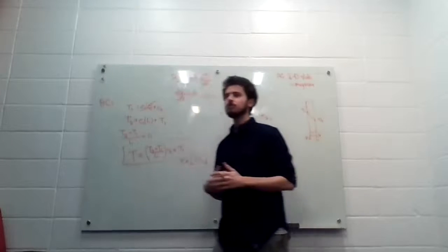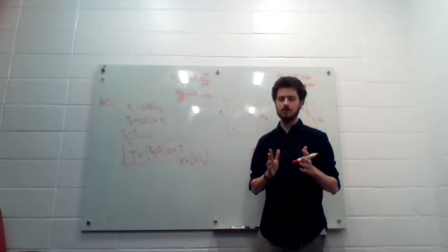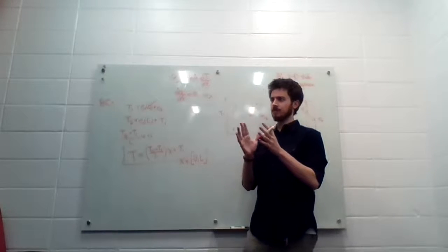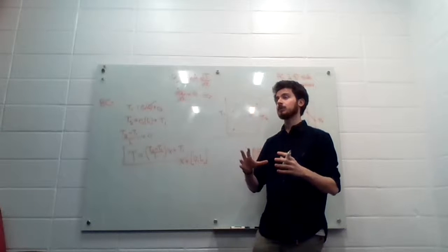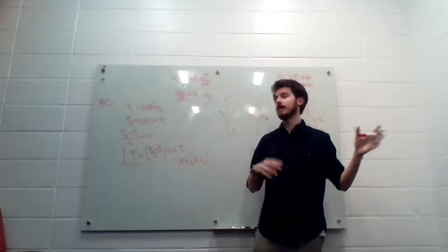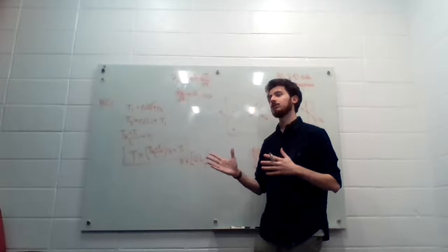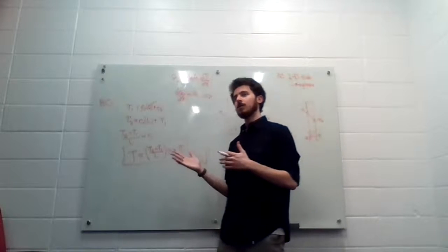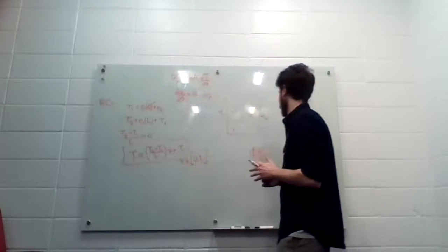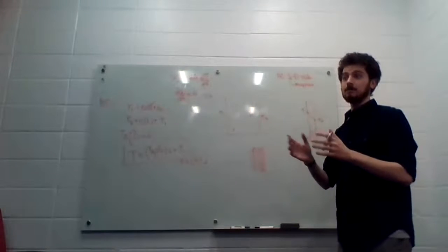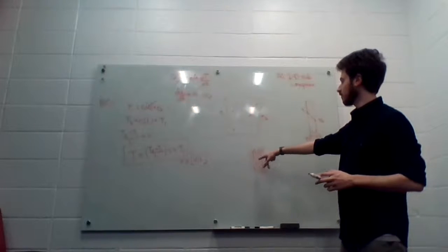So something that's useful is if you can describe the wall in terms of, if you could abstract the wall into something that's independent of temperature, then you can just apply different temperatures to that wall element and you'll know how much heat will transfer. So we want a generic way of describing the wall that's independent of temperatures actually being applied.